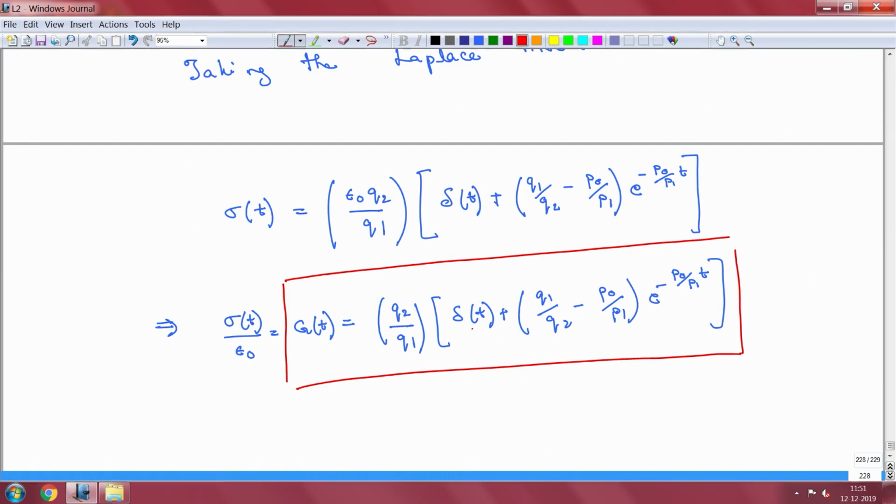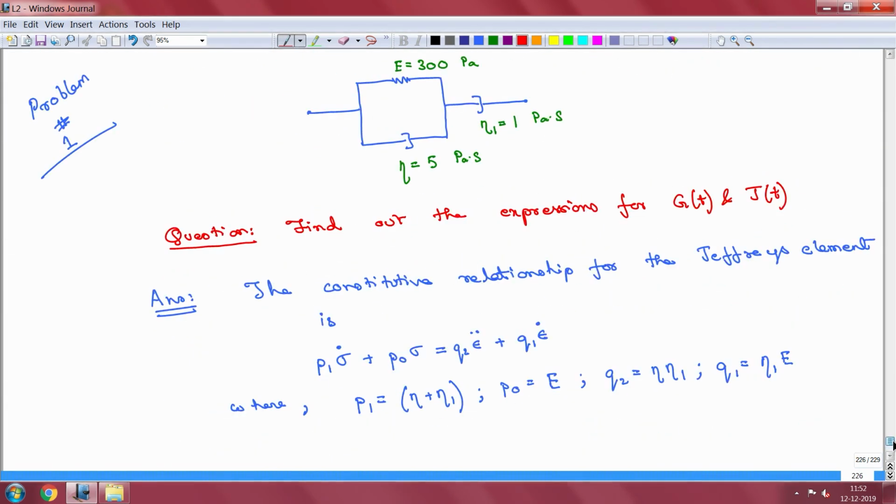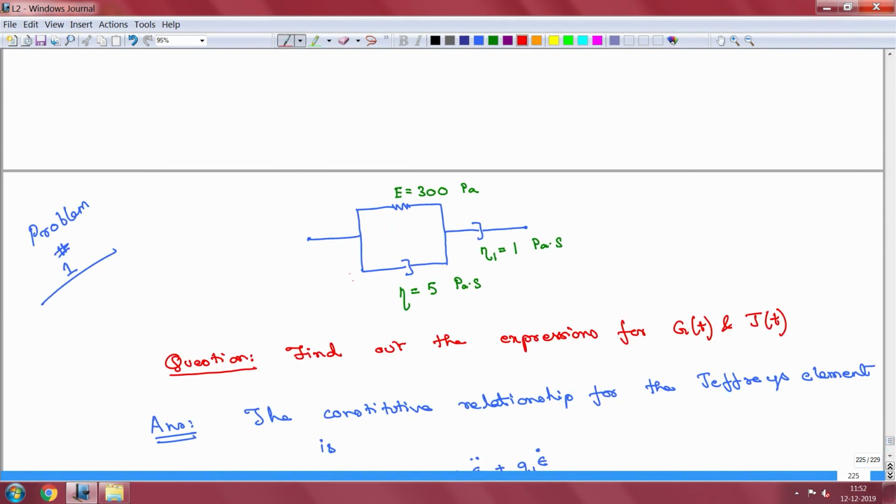Yes. You can see this is a Dirac delta function, and then you have a term that is exponentially decaying with time. So, this entire form is going to go over to 0. So, this does qualify through our simple sanity check that this form indeed looks at least correct, and if we have done the algebra right, then the algebraic expression is exact. One more thing, you see that this strange Dirac delta function is there, right, and what is the physical reason for that? The physical reason actually comes from the fact that this is a fluid element.